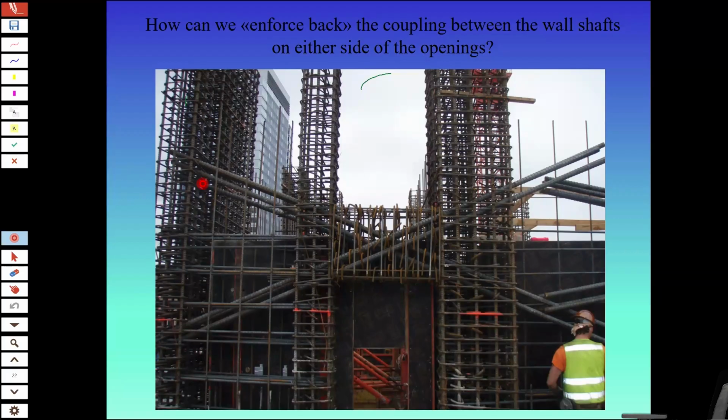And you also see these two shafts, how heavily reinforced they are. You see there is one main stirrup here, but you can see also hooks in between because you have to connect all the reinforcements. So the design of this kind of details is actually very demanding.